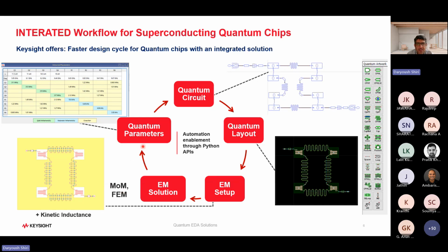After that, instead of extracting S-parameters and taking them to your own MATLAB or Python code, and figuring out which parameter is which, how the qubit-resonator coupling is calculated, how this capacitor, that capacitor, everything, just by pressing a button, you can extract this table and see the most important parameters. And from that, extracting the rest of the parameters is easy.